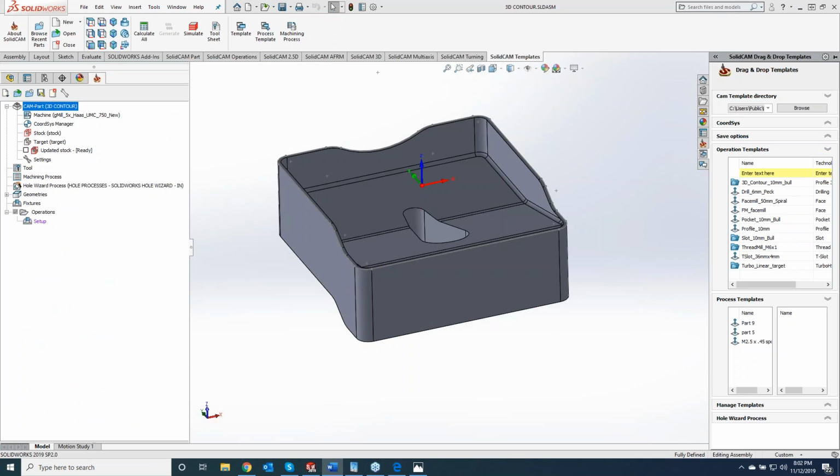All right, we'll get the ball rolling here with Contour 3D. If you think of it as a profile operation, Contour 3D adapts for Z levels. It will go up and down in Z depending on your chain, whereas on profile, when you define your geometry, it doesn't matter if you go up or down, it just brings it all onto one plane. In Contour 3D, it's going to follow the exact contour of the surface. I'll show you an example of that.